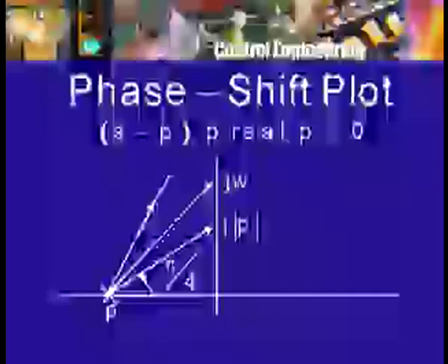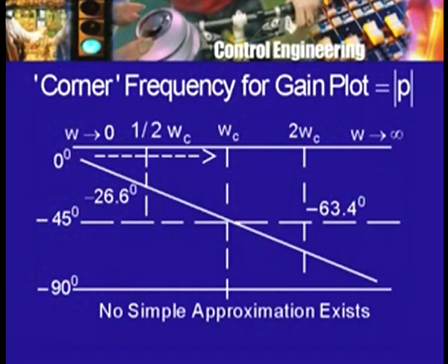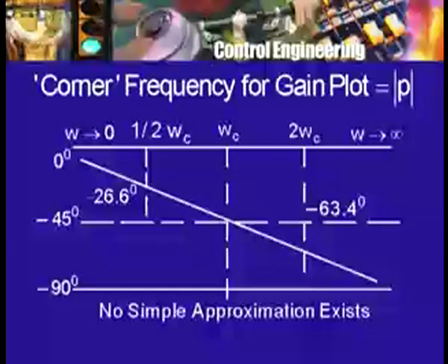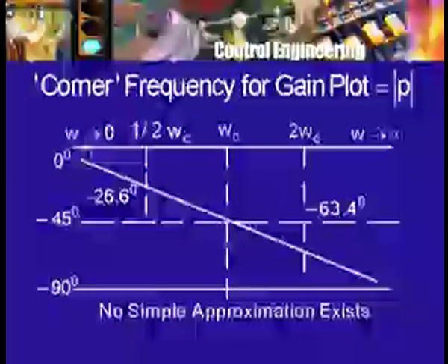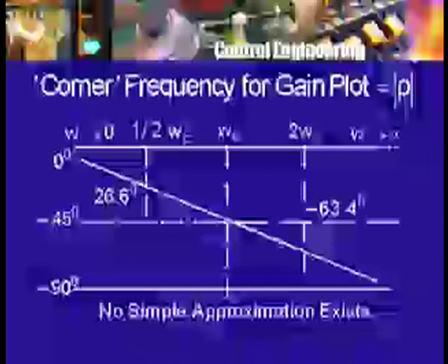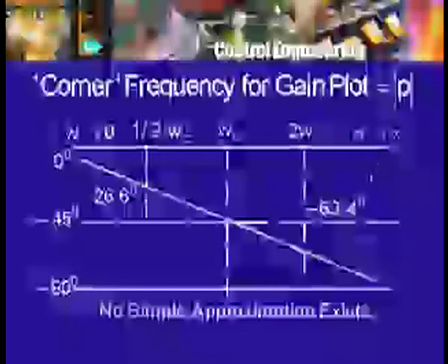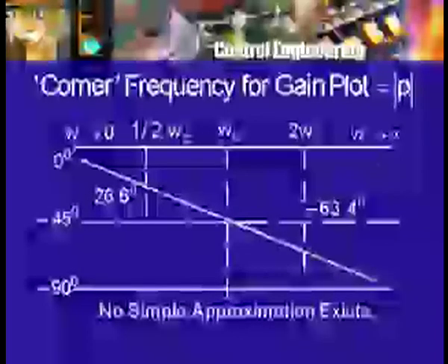So, from this we know that if I were to plot, and now I am not showing the scale of the omega axis as logarithmic because there is no log occurring anywhere, I am just drawing a horizontal line to show the omega scale. The phase shift is going to vary from nearly 0 degrees or a small negative value towards the low frequency end, so omega tending to 0, to minus pi by 2 for omega tending to infinity, that is the high frequency end.